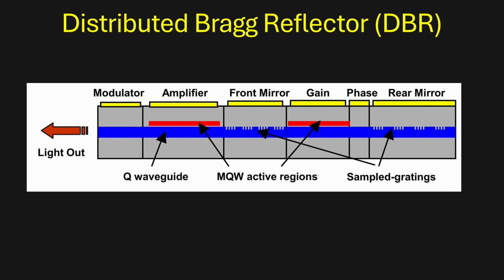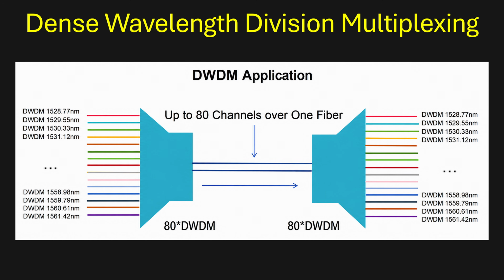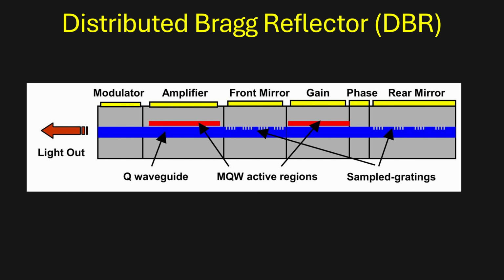undersea cables. These are also edge-emitting lasers and have a very similar design to DFB. The difference is that in a DBR laser, the active emitting section and reflective grating sections are separate. This allows for maximum tunability since each section can have the current and temperature adjusted independently. Tuning the wavelength is helpful for dense wavelength division multiplexing, as in undersea cables, because you do not need to design a new diode for each of the dozens of channels sharing a fiber. These often have long passive cavities, phase tuning sections, and more complex control systems that can achieve better line width and other performance metrics, but at a higher cost.